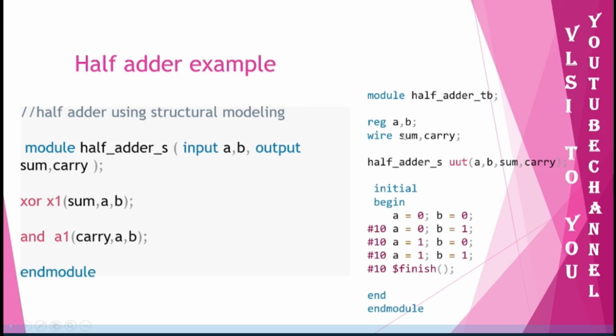Now what you do after this is instantiate the DUT in the test bench. That means you need to connect them. How are you going to connect? This is the module instantiation. So this is my half_adder_s, which is my DUT, and I am connecting it to the half_adder_tb. If you see here, this is my half_adder_s, instance UUT, and a, b, sum and carry. So this a is connected to this, b is connected to this, sum is connected to this, and carry is connected to this. So you're connecting it with the module instantiation.